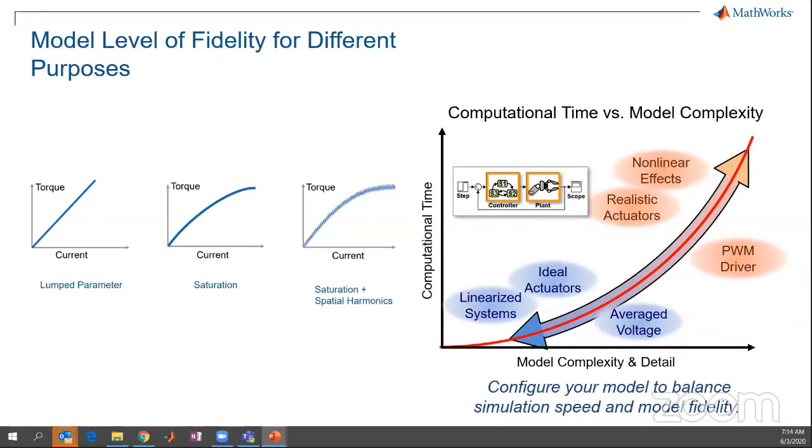And if you are an electrical engineer who is focused on component level simulation, like SPICE level simulation, you can choose the detailed level of simulation, including some saturation effect to do more harmonics analysis. The trade-off: a lumped parameter linear model takes less computation time and gives fast simulation, allowing you to run large system level simulation. As for modeling complex and detailed component level simulation considering the non-linear effect, it will take longer, but at the same time, it can give you more correct, realistic simulation results.